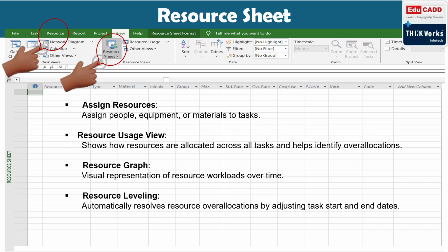But practically we cannot arrange the manpower like this, right? We have to have the same quantity of resource for a duration. For example, at least for 1 month we should have the same manpower. Then only can we manage the resource. Otherwise, we will be preparing the schedule and practically will not be able to achieve it. That is why we have to level the resources.